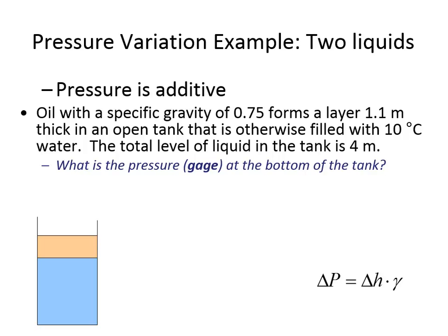Okay. So it would be 8093.25 pascals plus the distance of 2.9 meters through a fluid of water. So we have the 9810 newtons per meter cubed. And that increase is going to be another 28,449 newtons per meter squared.